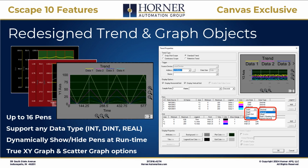These objects have been redesigned from the ground up. So for instance, with trends, you can now have up to 16 pens on a single trend. You can have multiple y-axes if you choose. Of course, you can support multiple variable types. At runtime, if the operator wants to zero in on one particular trend line or one particular pen, they can dynamically turn off or hide pens which might be getting in the way visually, and then show them again when they're done. So dynamically showing and hiding individual pens at runtime is a big capability as well.